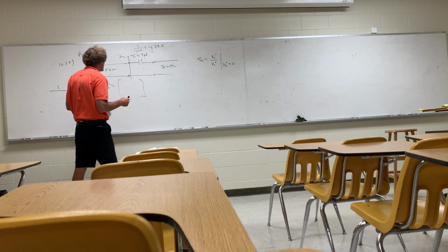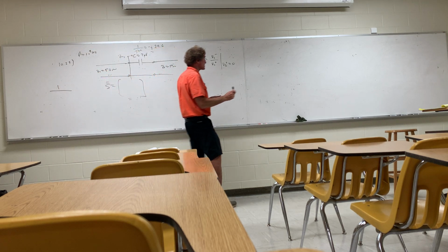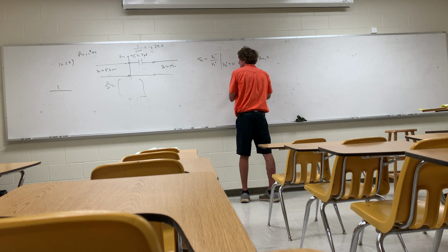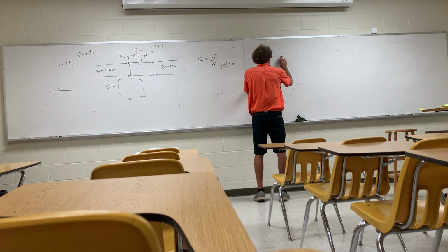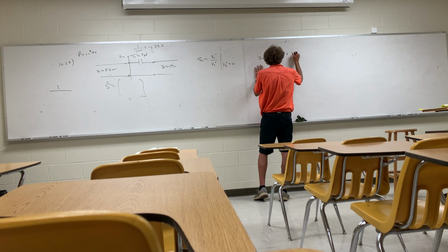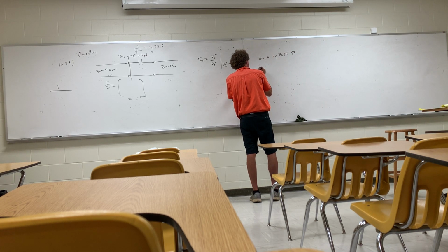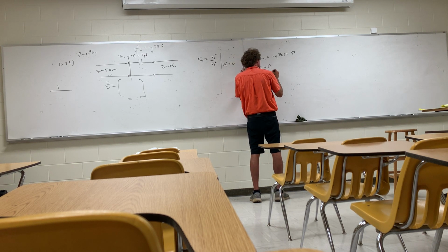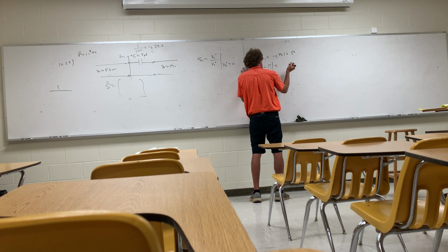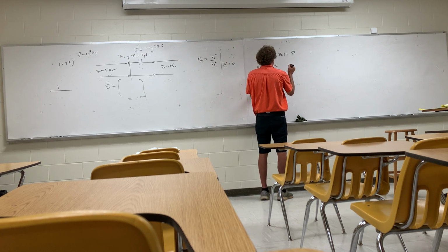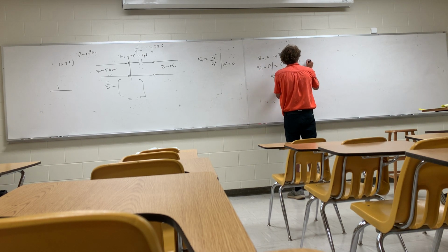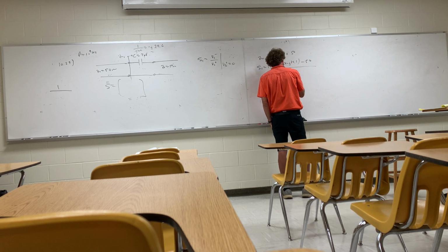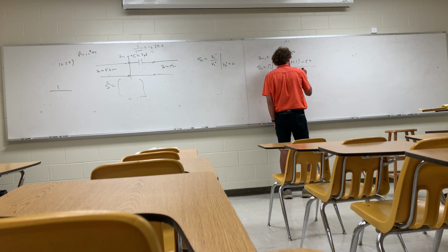So now what is the input impedance right there on port 1? It would be that plus 50, wouldn't it? So I'm going to write it down. The input impedance is going to be 50 minus j79.1. So what would S11 be, which would be the reflection coefficient, assuming V2 plus equals 0? It's the impedance I'm going into, 50 minus j79.1, minus the impedance I came from, which is 50, over the sum of the two, which would be 100 minus j79.1.